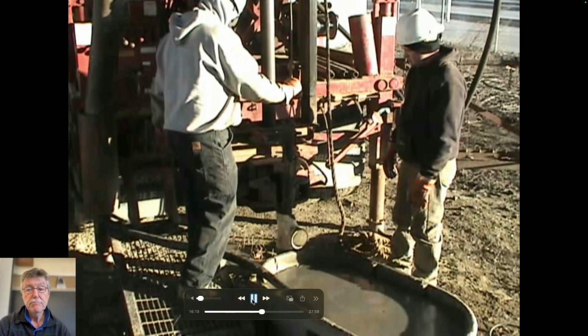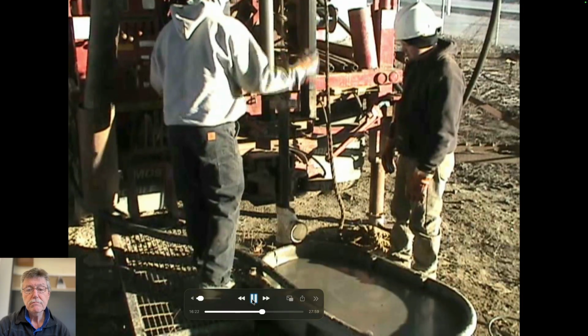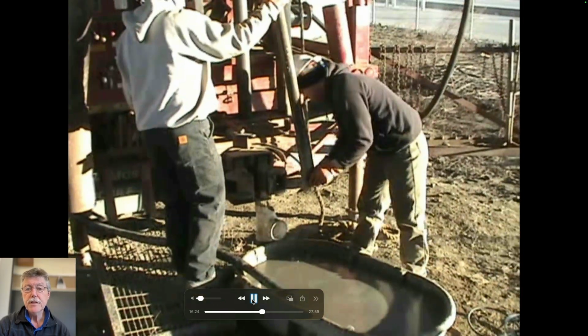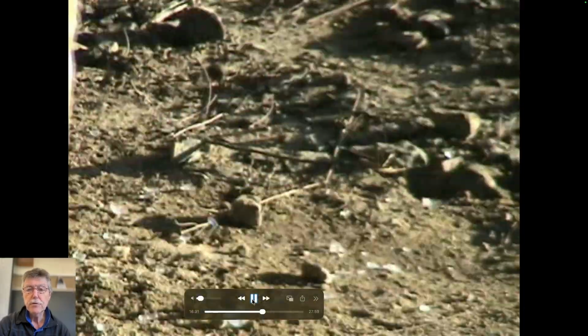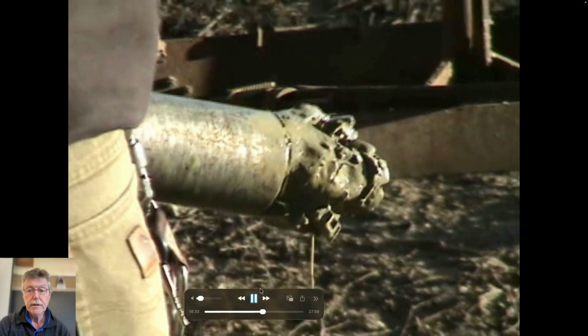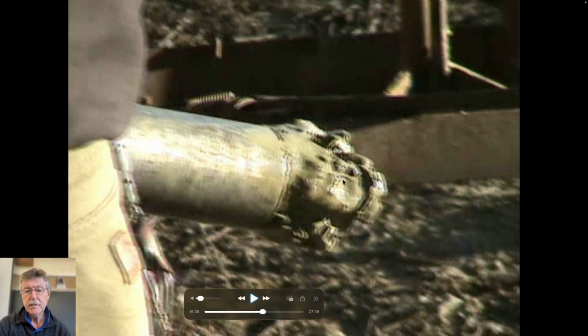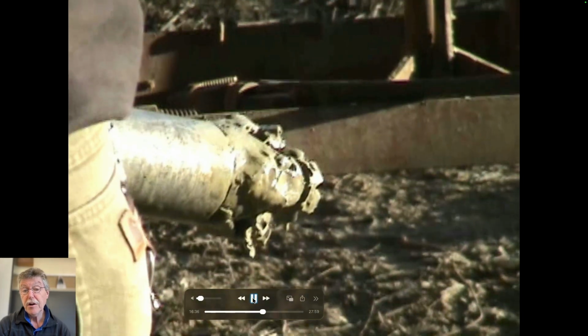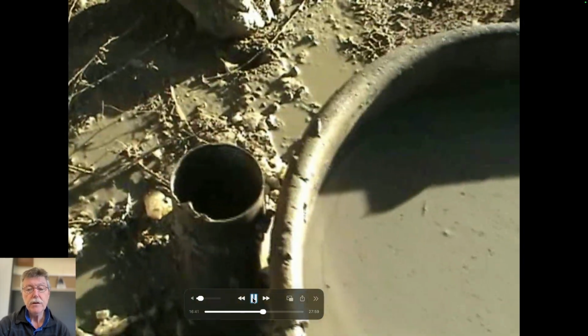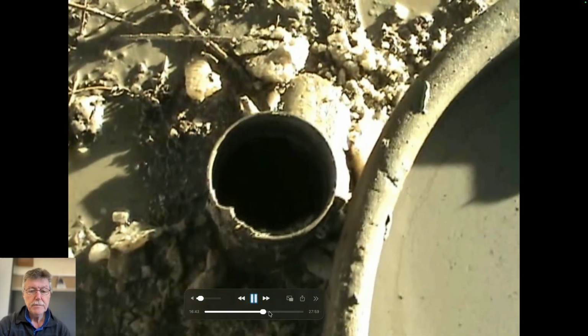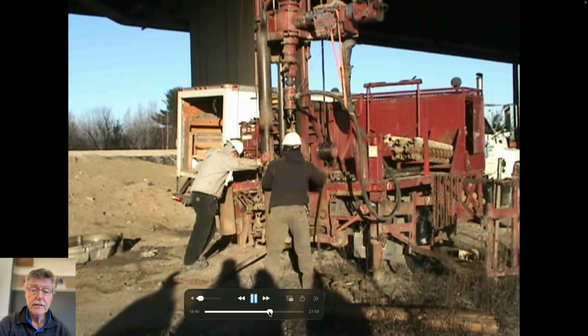This is pulling something out. Just lifting it on a winch. Not sure what that is. A tricone bit, a small bit. There you go. So you see the three cones, which are on spindles. They're not driven, but they merely rotate at the bottom. This is drilling through clay. This never went into rock, so it's just a mess. Some December near Boston.